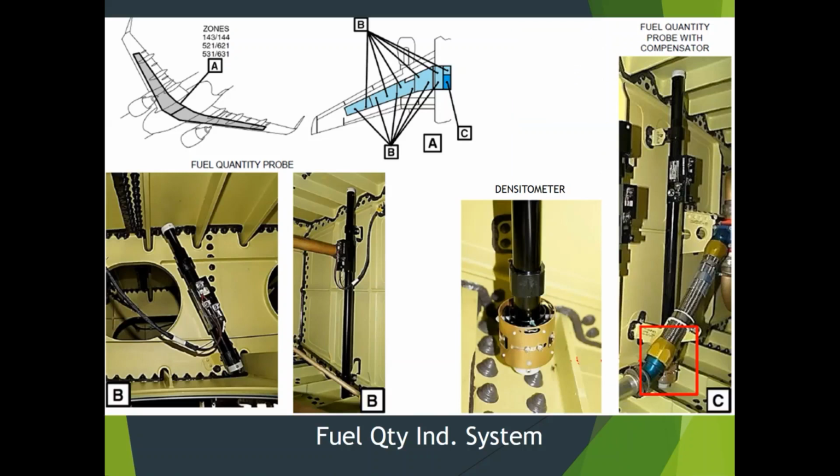Maybe you have 2 or 3 different sizes. And if you get to a point in the wing where it's a little bit too thin, you can take one of the longer probes and install it slightly sided. That's not going to change how the fuel changes level in there. When they figure out the volume to pounds correction, that's factored in here.